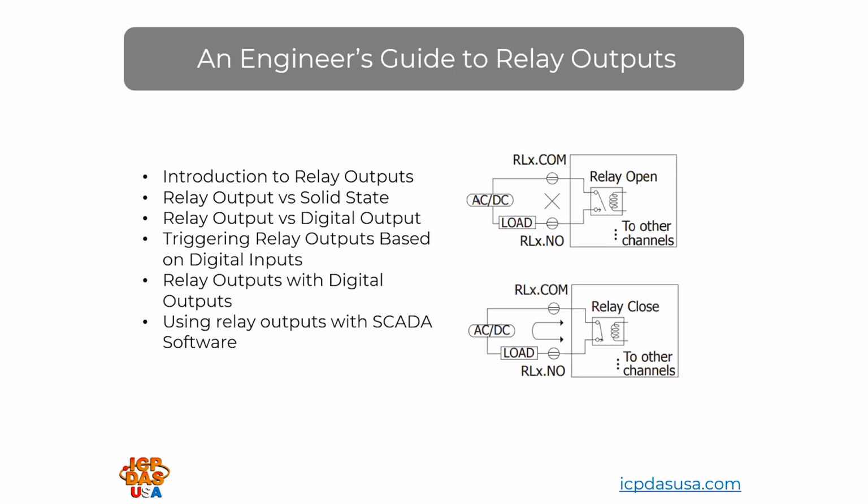Relays are switches that open and close circuits. When a relay contact is normally open, the contact is open when the relay is not energized. When a relay contact is normally closed, the contact is closed when the relay is not energized. Applying electrical current to the contacts changes their state.